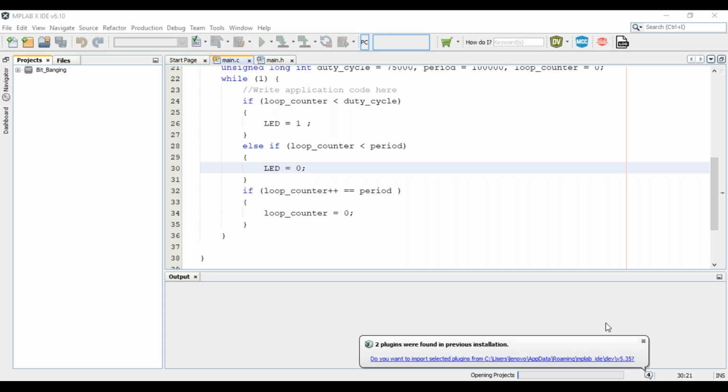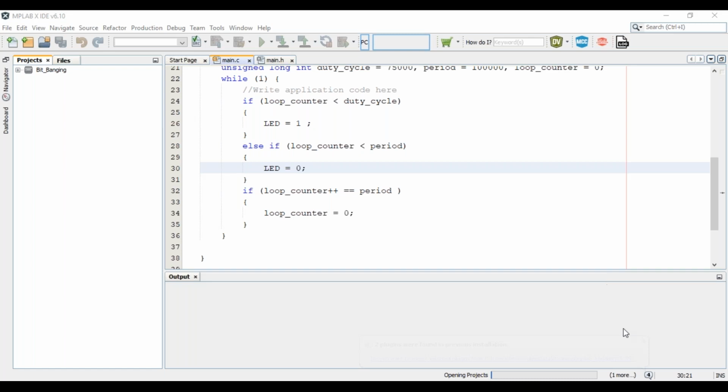Writing PSA with the value 1 will not affect the timer 0 module because I'm assigning the prescaler to the watchdog timer, which is already disabled. So I don't have any other option: I should either write a 0 or a 1, and writing 0 would have an effect. So I wrote PSA with the value 1.